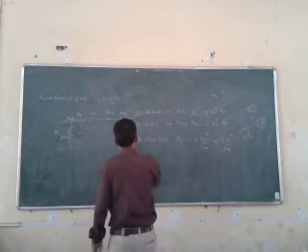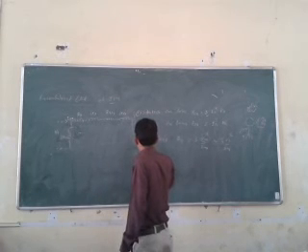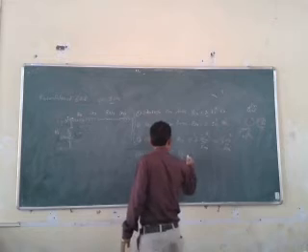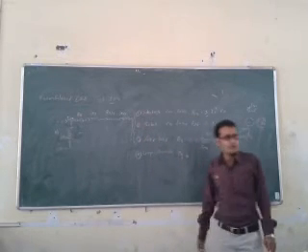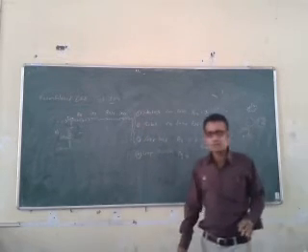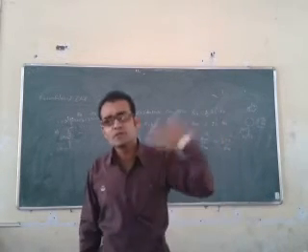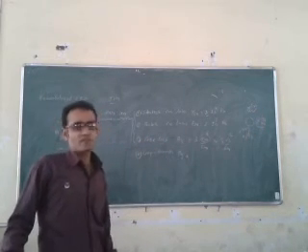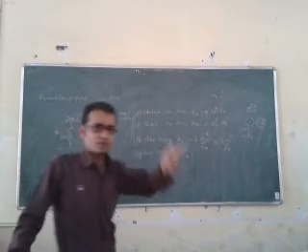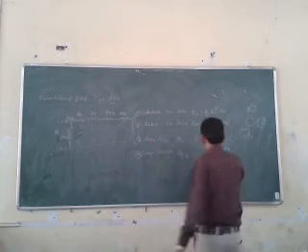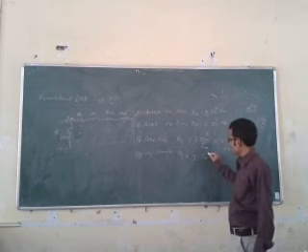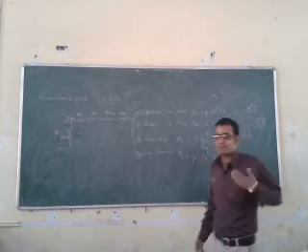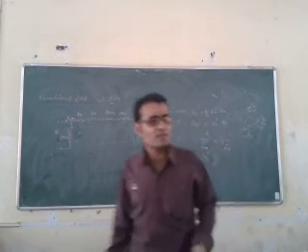Now the next point is gap power. Gap power is the power which is transferred from the stator to the rotor. So it is equal to 3 times Ir square Rr divided by, once it is transferred to the rotor, there may be generation of slip.